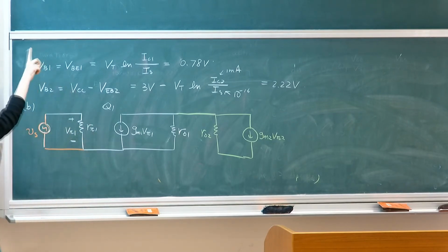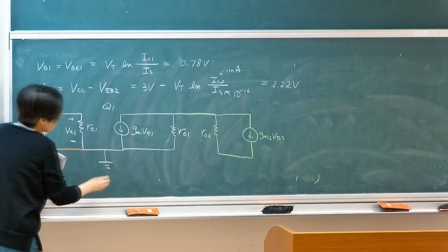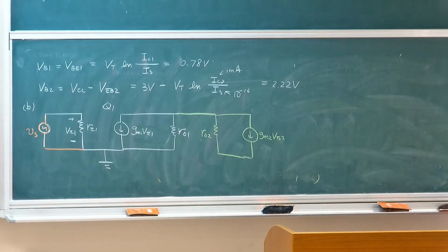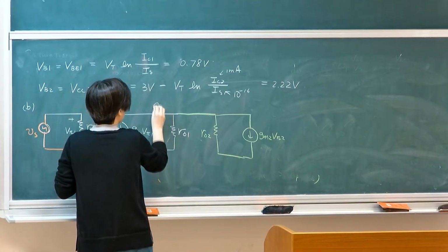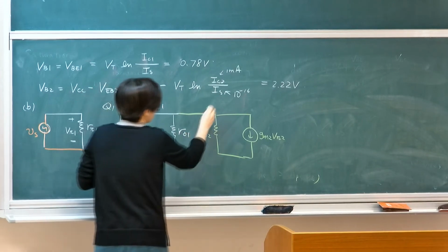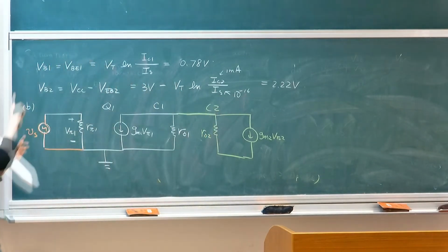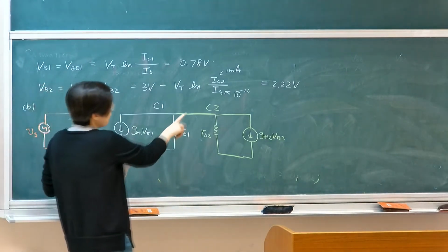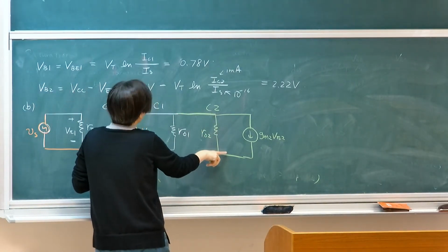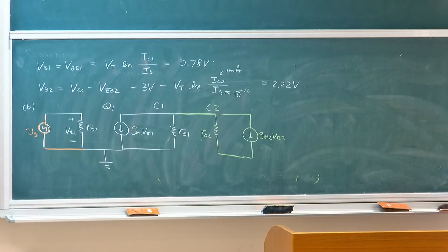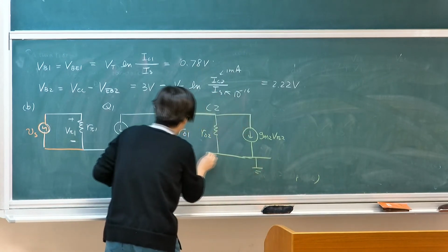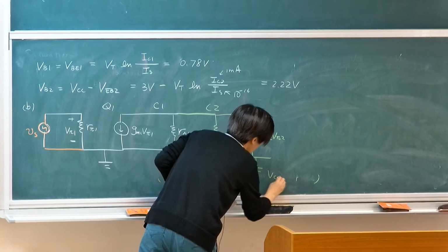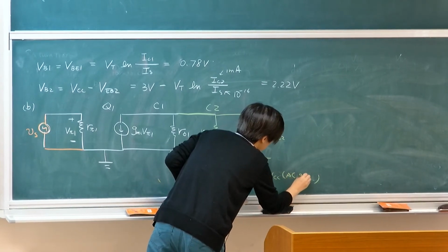And this is the emitter terminal. The emitter is grounded, right? And the other side, remember this is collector 1. This is collector 2. So collector 1 and collector 2 are connected, and the emitter terminal of the PNP transistor is grounded, AC ground. This is VCC, so you can assume that they are ground. This is VCC, which is AC ground. Again, small signal.